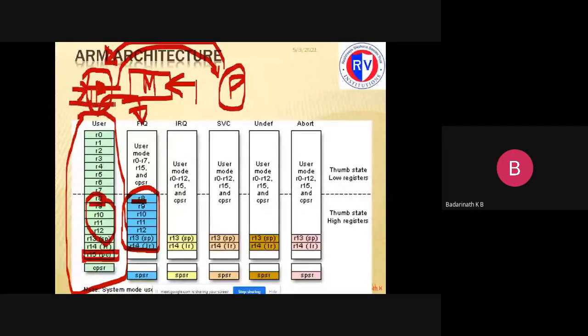Again a request came from another interrupt device, a sensor, which is not very urgent, but we say that you give the service. That's what it's asking the microcontroller. So now you have to attend what is called the IRQ mode. There is another program written and kept in the memory to do the service for this IRQ. So again you have to stop wherever you are, go back and execute this program, and do the service for this device which has raised an IRQ request input.